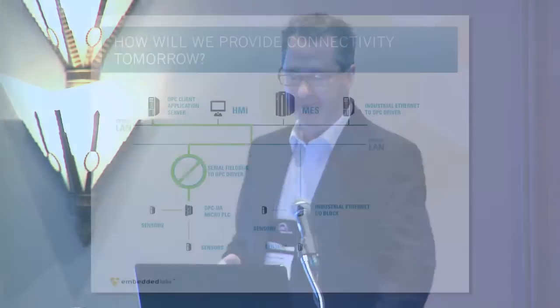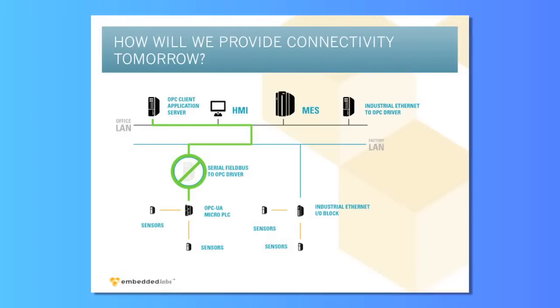Or maybe, in the case where you're retrofitting onto an existing system, this is something you might do. But if you're putting in a new system or a new piece of equipment, maybe you can go better than that and get rid of the gateway altogether and purchase a PLC which actually has OPC UA directly embedded inside it. Now, as I said before, to put OPC UA in a device, you need a chip that costs less than $5 in quantity.